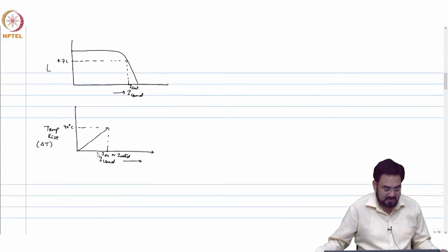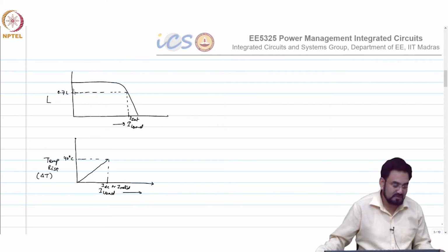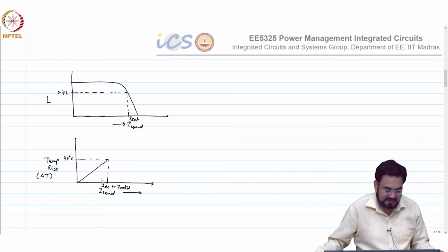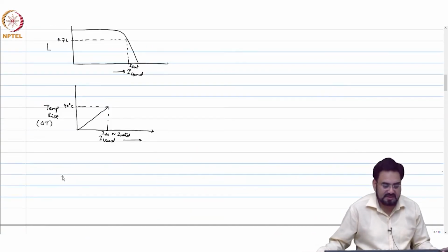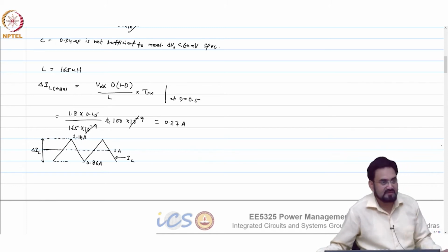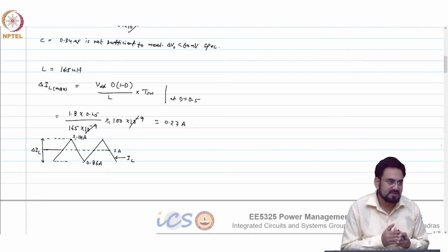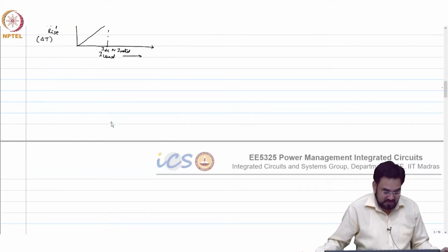Okay. We were talking about this inductor and capacitor, how you choose them, how you look for I rated and I saturated, or saturation current, for the inductor. The saturation current is when the inductance value drops by 30%, and the DC rated current is when the temperature rises by 40 degrees. There is also something called self resonance in the inductor. Because these inductors have parasitic caps, if you remember the models we talked about, based on those parasitic caps they will have a self resonance. So when you choose an inductor, you have to make sure that its self resonance is much higher than your switching frequency, otherwise you won't get any value of the inductance. Basically, the inductor is dead when it is resonating. So those were the things you need to consider.